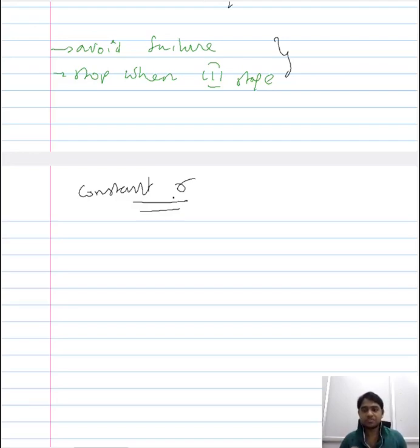So constant stress was one of the conditions that we ensured is imposed on the material during creep testing. This means that before the failure of the material, when the geometry of the material begins to change, or when necking sets in, the stress that is required to deform the material also correspondingly changes. And since we have used a constant stress condition, the tertiary stage is still prolonged. So when you want to test the failure of a material using a conventional creep testing setup, it will be unnecessarily prolonged, considering that we have assumed a constant stress condition for the creep testing.